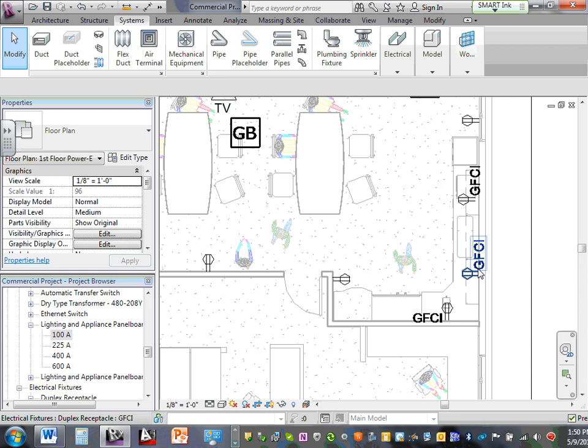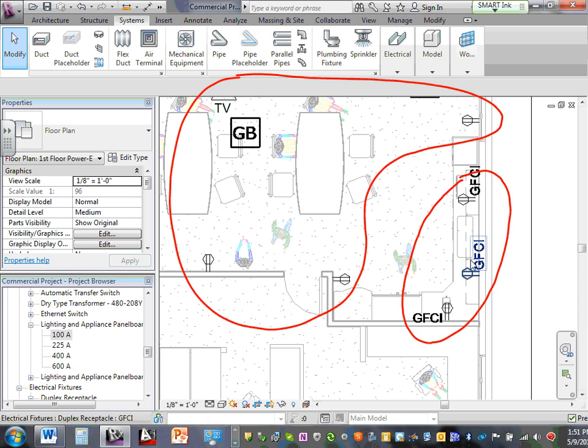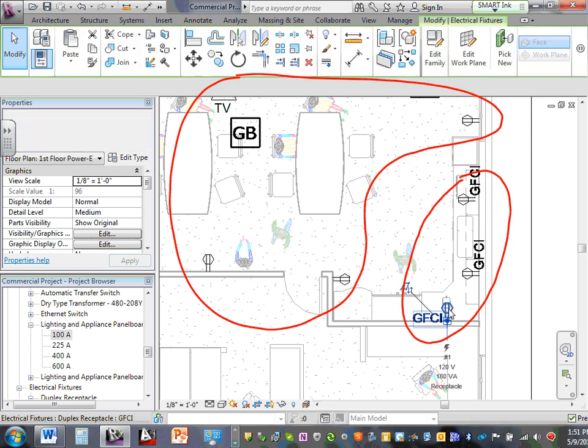I'll tell you about the design later, but for the time being, I'm going to tell you what you're going to circuit. I decided single-handedly to grab all these countertop receptacles right here and put them in one circuit, everything else in this room in a second circuit, and the other room in a third circuit. Three circuits. Why did I decide it this way? It's coming. Now, do me a favor, click on the first one.